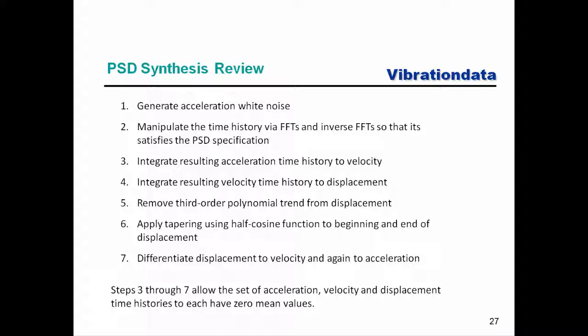Anyways, I take that displacement function that's been cleaned up from step 6, differentiate to get velocity, then differentiate again to get acceleration. So that's how I come up in step 7 with a corresponding set of displacement, velocity, and acceleration, where each one of those 3 signals oscillates about the 0 baseline. And that works out pretty good.